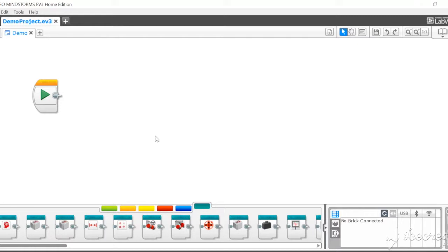RobotConfig is a block quite similar to init-run, but instead of doing things like resetting the sensors and variables, we use it to tell the program where things are on the robot. We initialize the ports of the motors and sensors, and later on we'll be setting other values. In our version, which you may need depending on how you've built your robot, we even have a variable telling the program whether the motors are inverted or not.